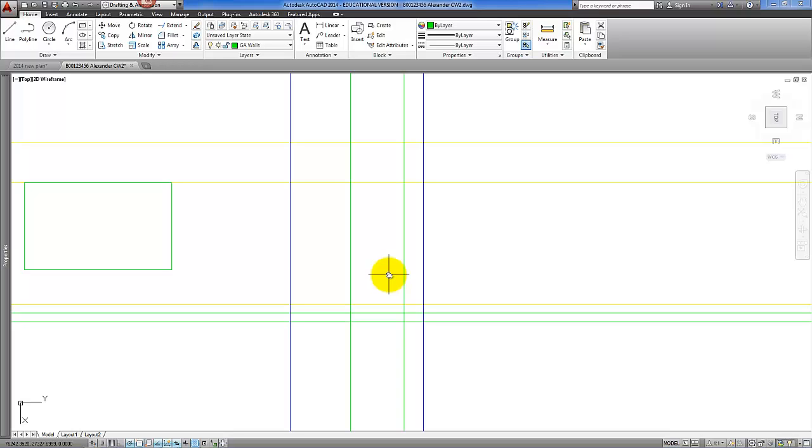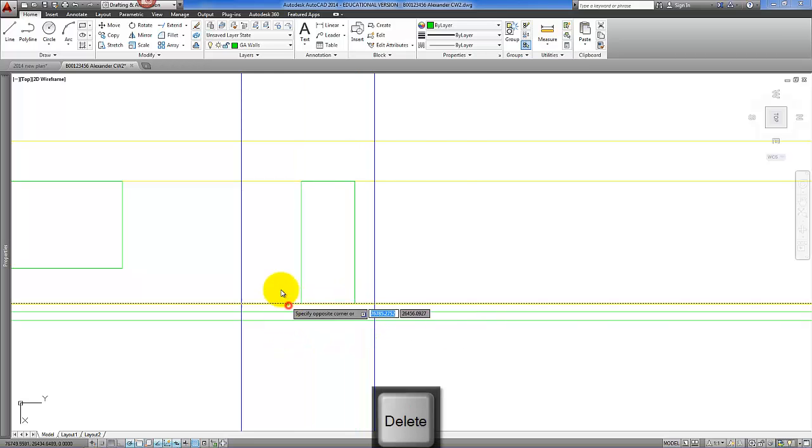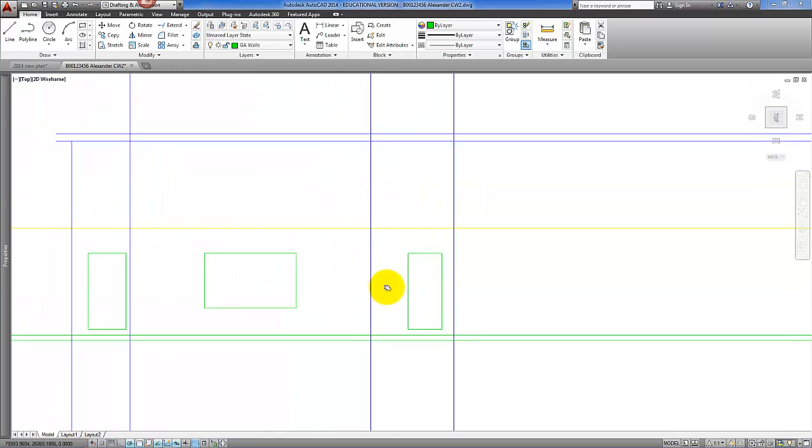This door could well be at a slightly lower level, then again it might not be, so I think we'll just leave the door head height as it is, and we can slope the ground outside afterwards. So we'll insert a door just at that level, and then we can delete the temporary lines.